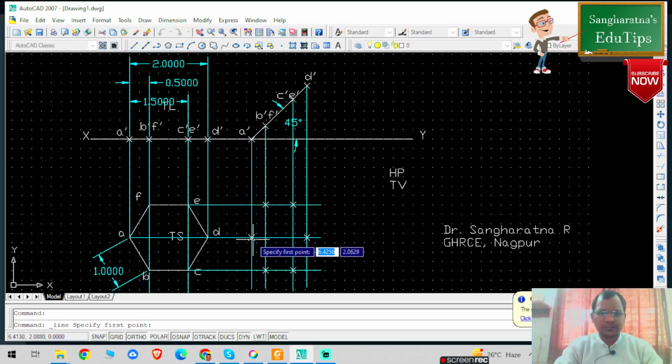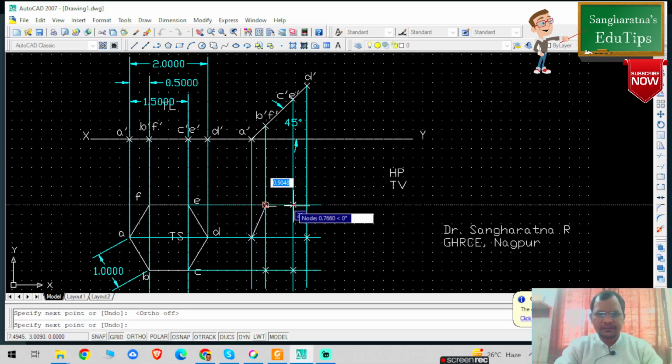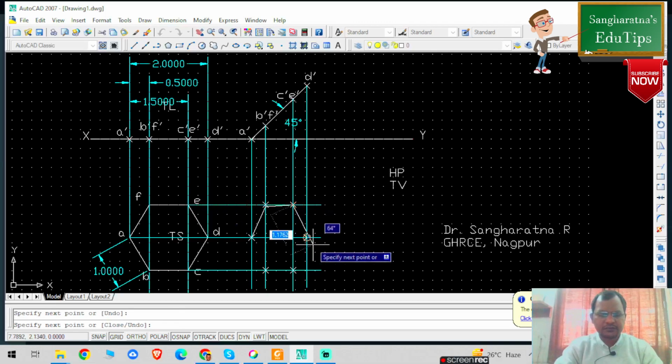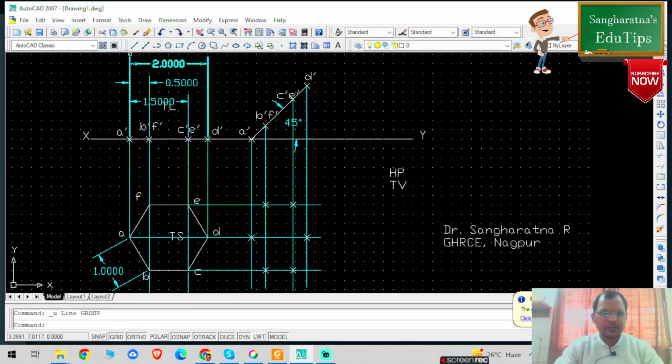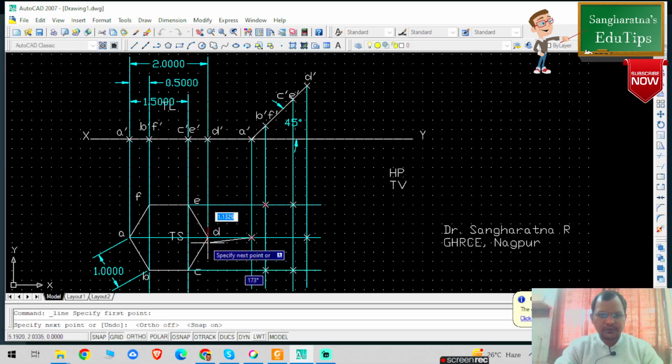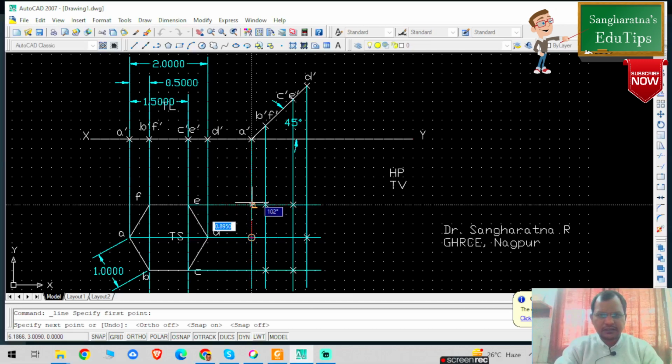Now I'm going to join these particular points with the straight line. So now you can check. I'm not going to mark the inclined line, so I'm unclicking ortho. So this is my first line, this is my second line. Press escape. You can check this is not correct. So press Ctrl Z. Now this is my first line, this is my second line. Ortho and snap: you can check this is my unsnap, and click on the snap.